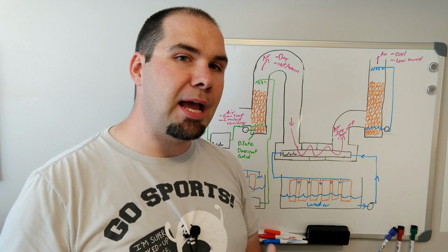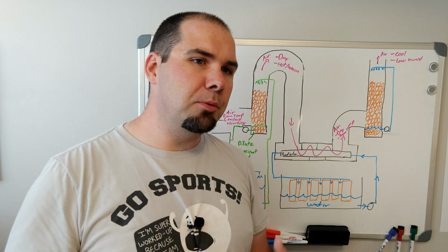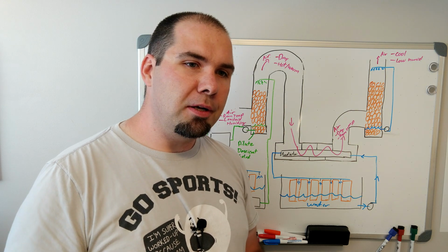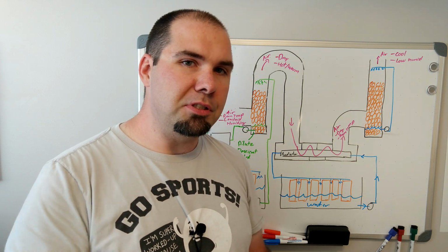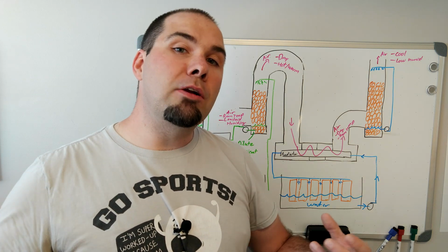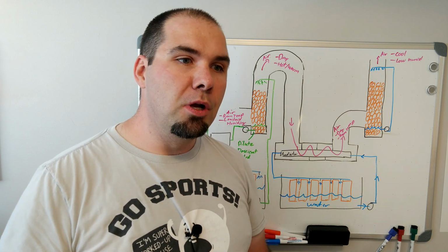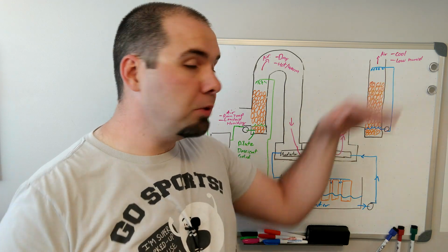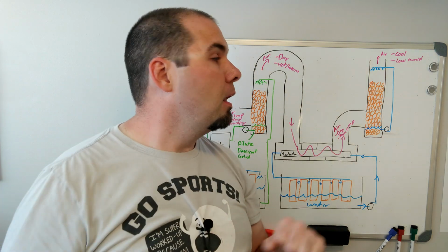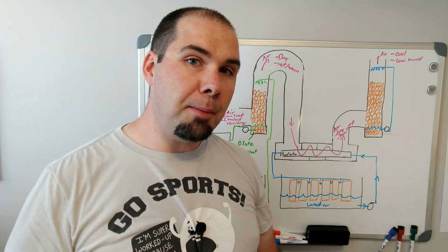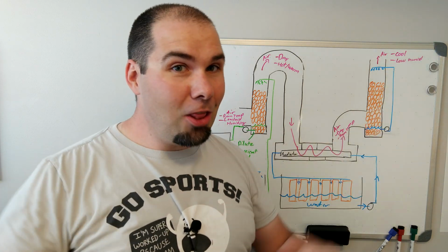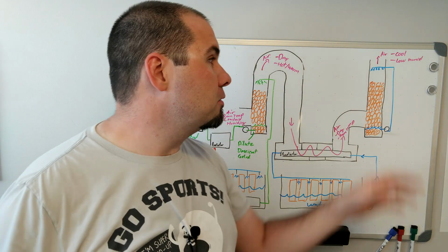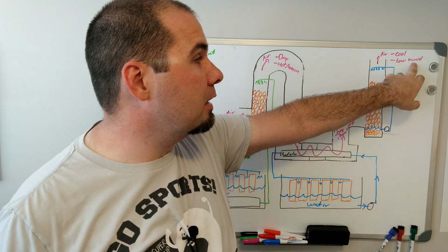And there's two mechanisms happening here. One is that we're measuring relative humidity. If you cool something, the amount of water that cold air can hold versus hot air is very different. Hot air can hold way more water than cold air. So as we cool it, that relative humidity is coming up. But we're also evaporating. So as we evaporate, even though it takes in a lot of energy, it's going with the airflow. So we're getting high humidity out of here.